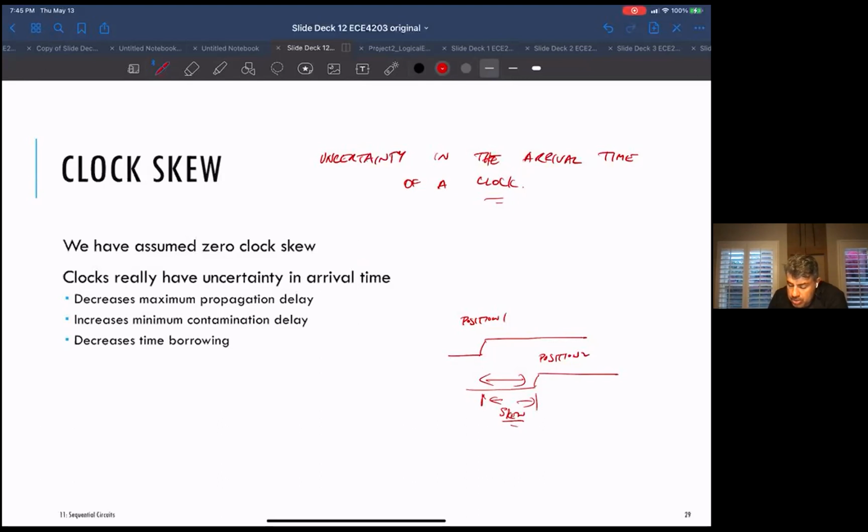It could be that things are arriving too fast or too late, and there's a bunch of stuff that comes into this. It could be the same for all your chips. It could be different for each chip you get out of the foundry, because they'll have some small variations in delay. It could change over temperature, because if there's a certain number of buffers the clock network is going through before hitting this guy, that delay changes over temperature or over supply. So those are the possibilities.